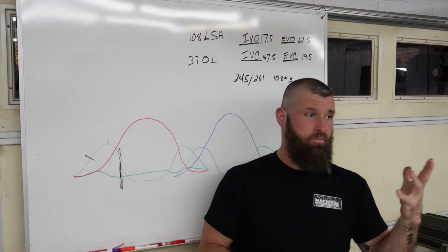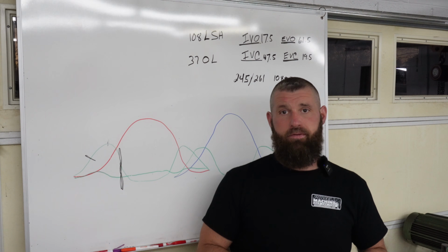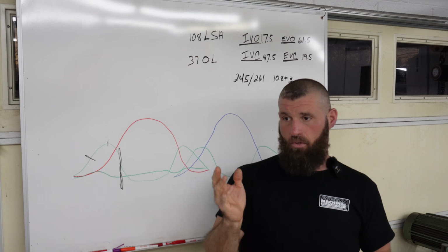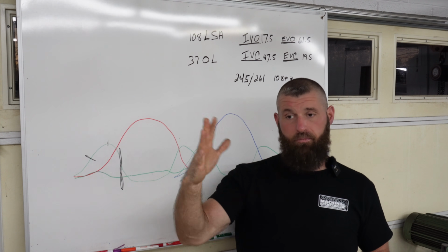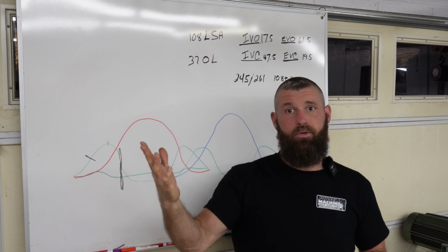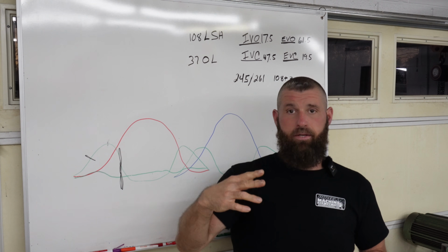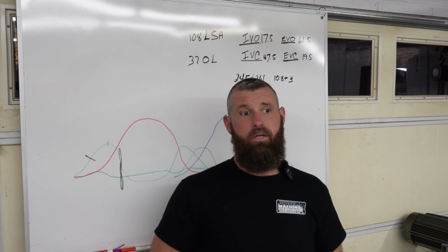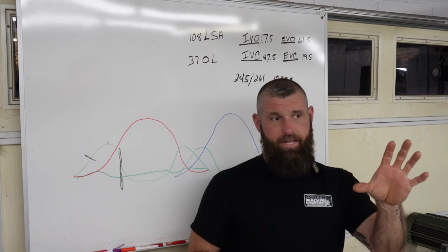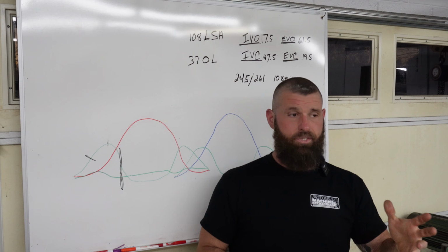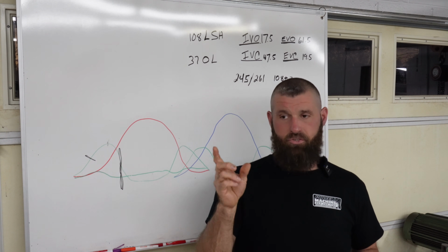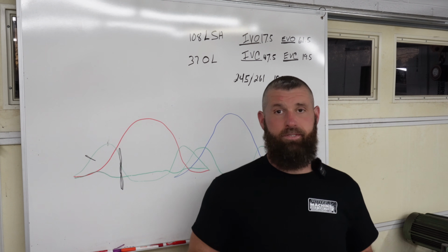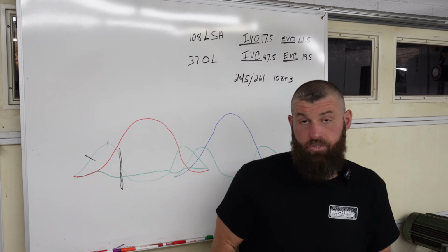If you drag race, you know that we're going to leave at 5,000 or 4,500 on the converter, and we're going to shift at whatever peak torque is. I mean, whatever peak, close to peak power somewhere in that window, and whatever that window is, set the averages on the dyno to that window and look at the averages as you're making changes, corrections, tuning. Look at that window and try to make the averages as high as they possibly can be. I don't even pay any attention to peak numbers. It's irrelevant to me because it's just useless information.